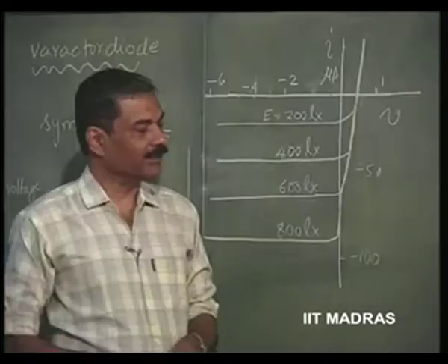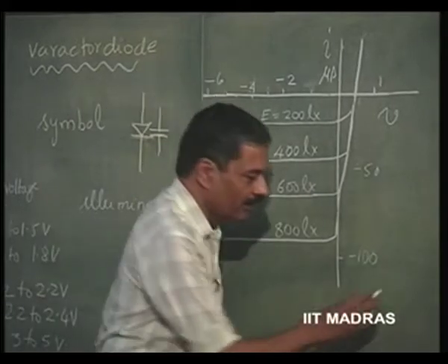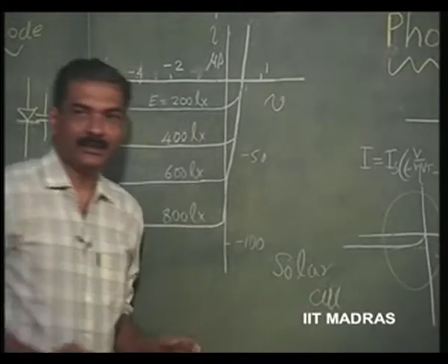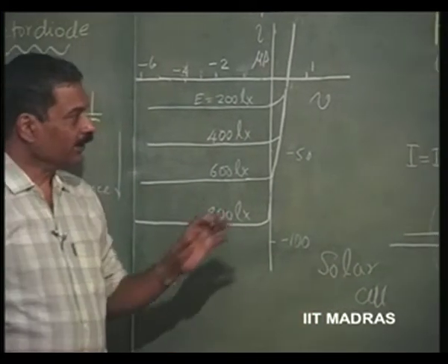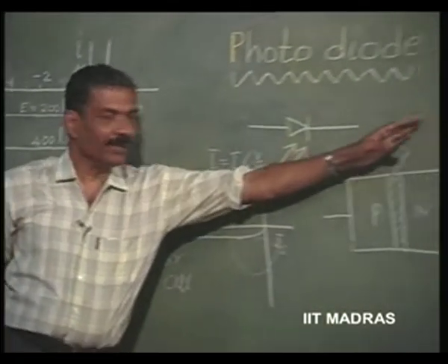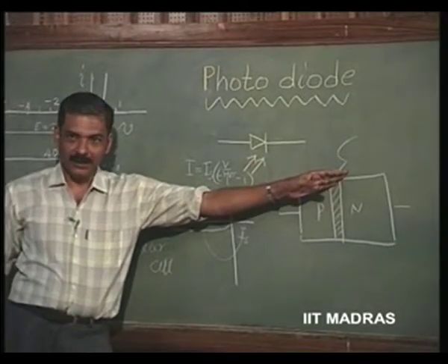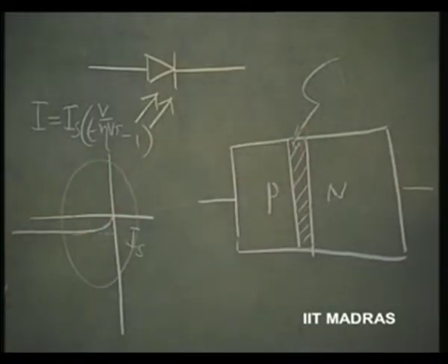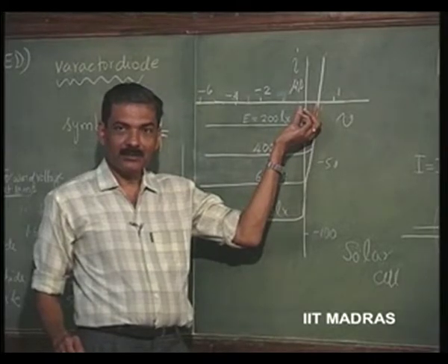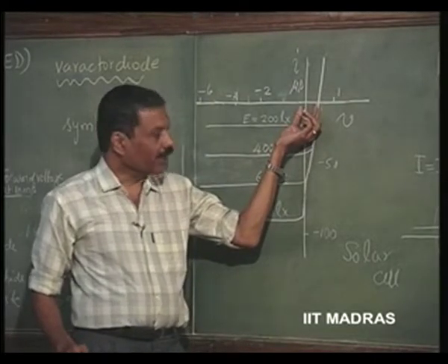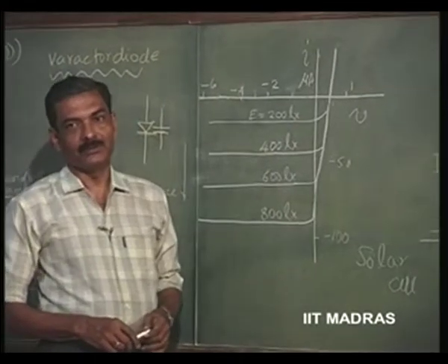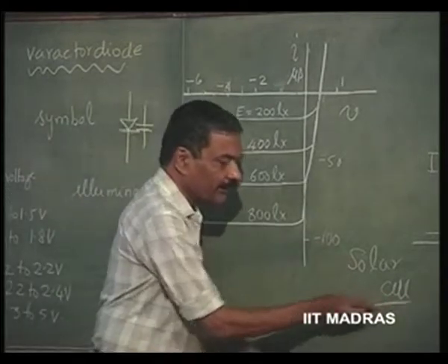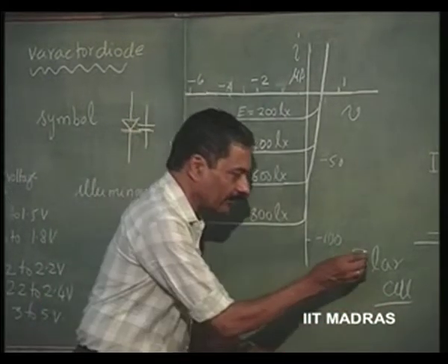That function of this photodiode is known as a solar cell. That battery, which you can sustain by giving an external source of energy to the junction constantly, has a junction voltage for silicon of typically around 0.5 volts, and you can now have a battery of your own. So, this is an important application of the photodiode as a solar cell.